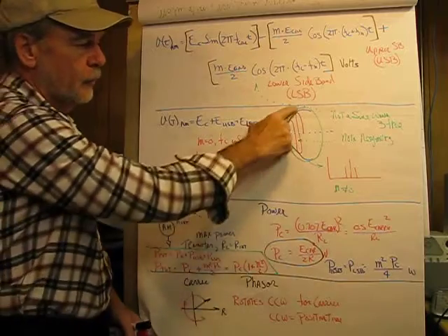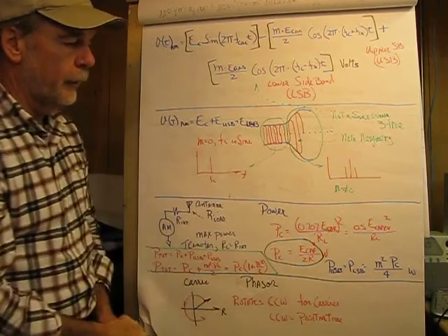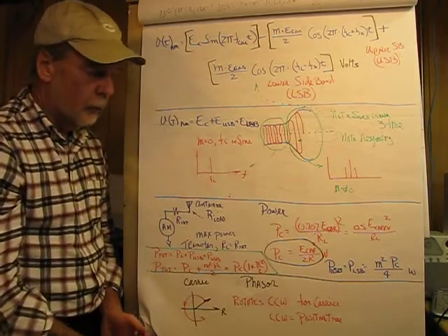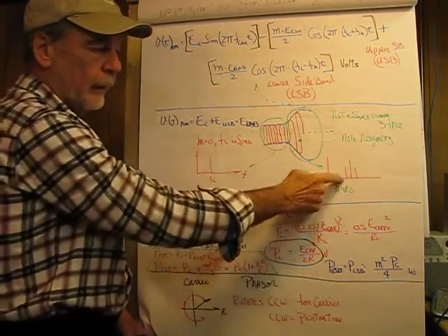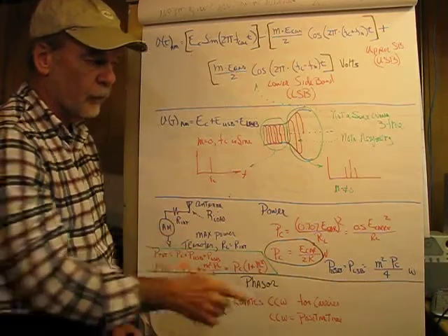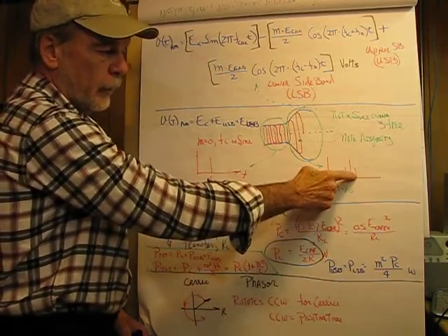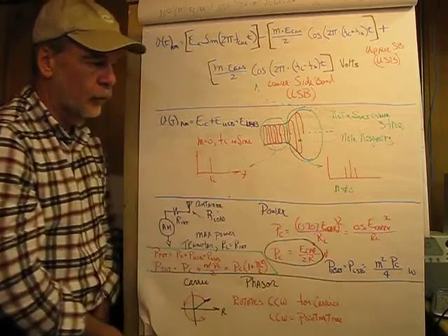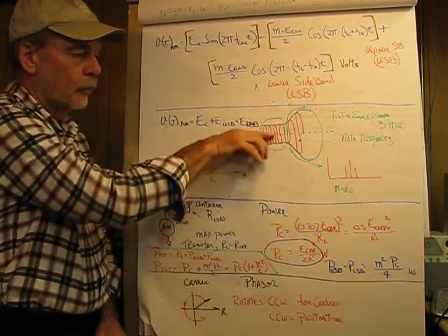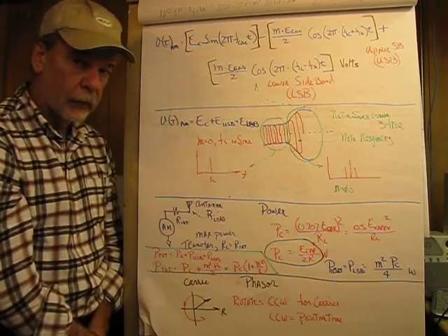And if we modulate it, referring to this area here, M does not equal 0, so we're modulating it, and now we have 3 sinusoids. Spectral spikes are always sine waves. One is the carrier, upper sideband, and lower sideband. And the upper and lower components of this relative to the 0 line are symmetrical.